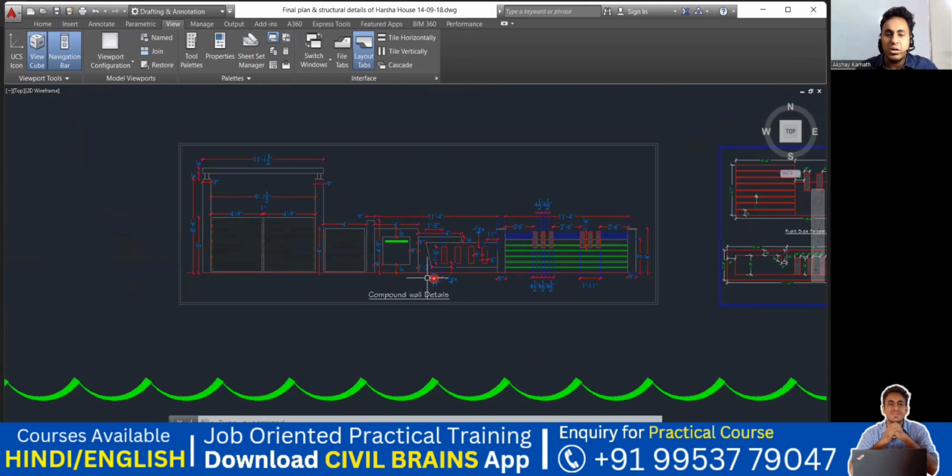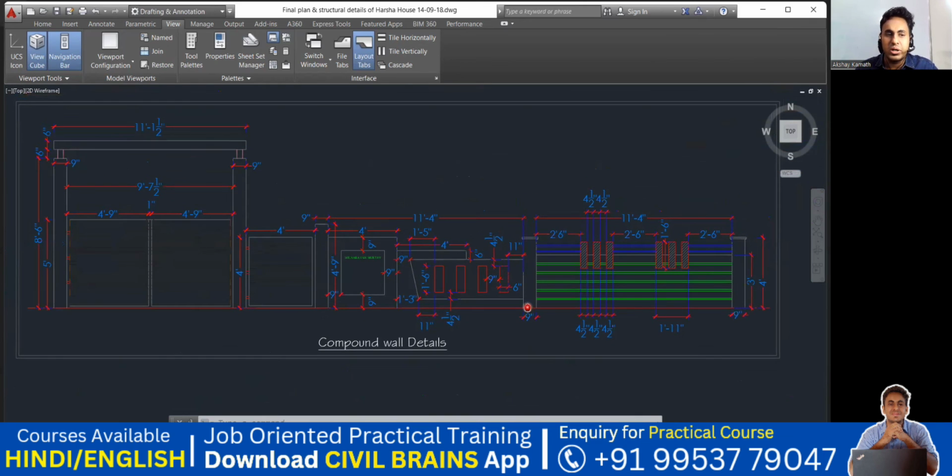See, this is your compound wall. This is the compound wall detail. This is a gate which is almost 5 feet in height. The top of your column will be 8 feet 6 inches. Then a 6-inch beam will come, something like a slab, a cantilever slab, so that it looks good. It's a 9-inch column on both sides.